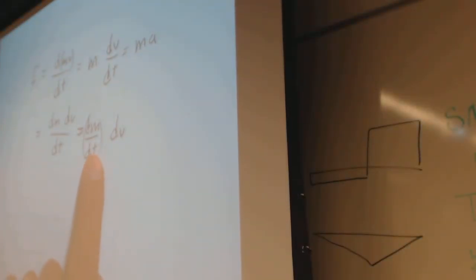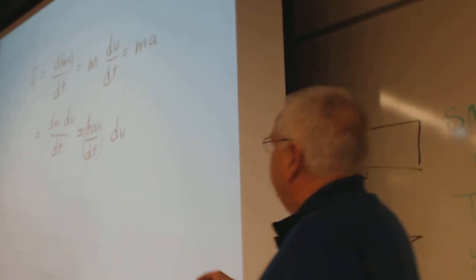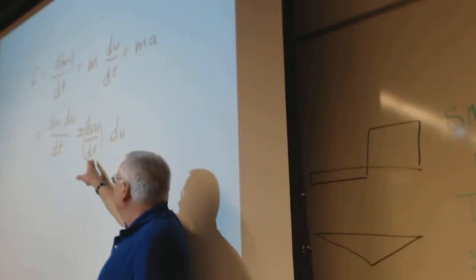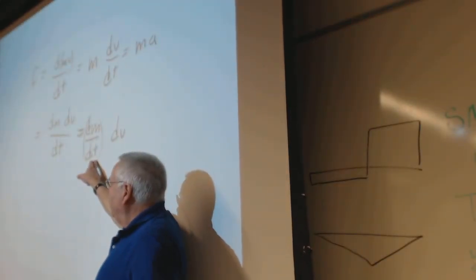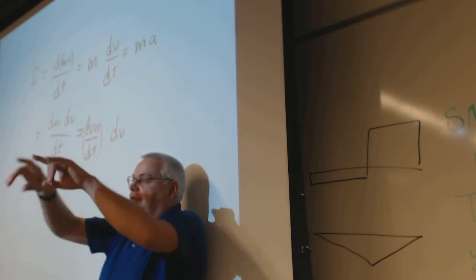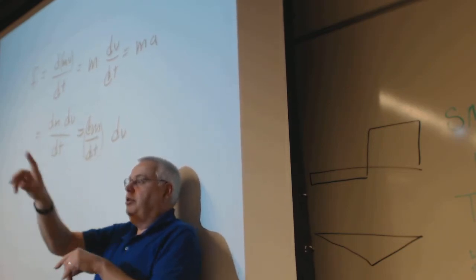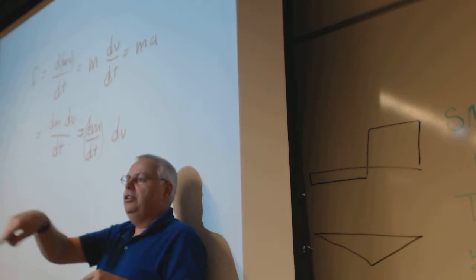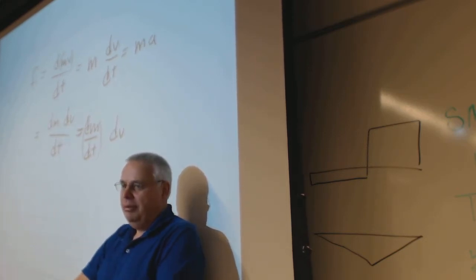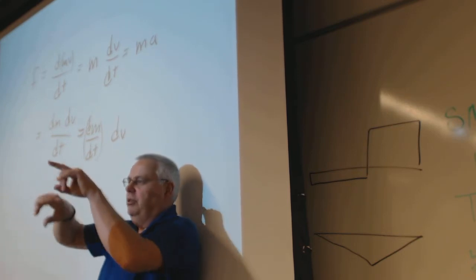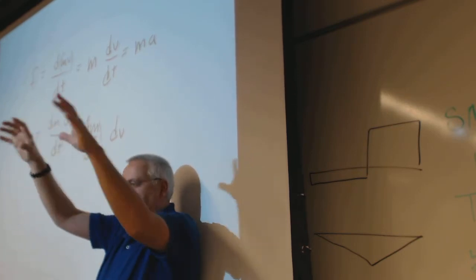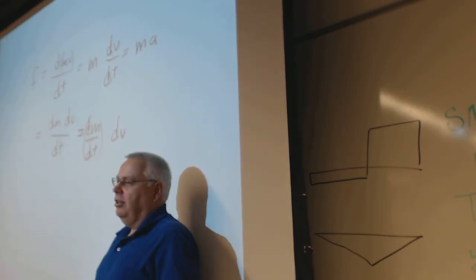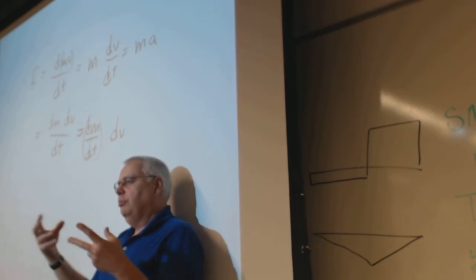If I can increase the mass flow rate by taking a shaft out front and putting a propeller on it, that's like the regional planes. They'll have a turbine engine turning a propeller. That's a turboprop. If you want to get more efficient, you put like 99 blades on that, put it inside a duct, and you have what they call a high bypass ratio turbofan engine.